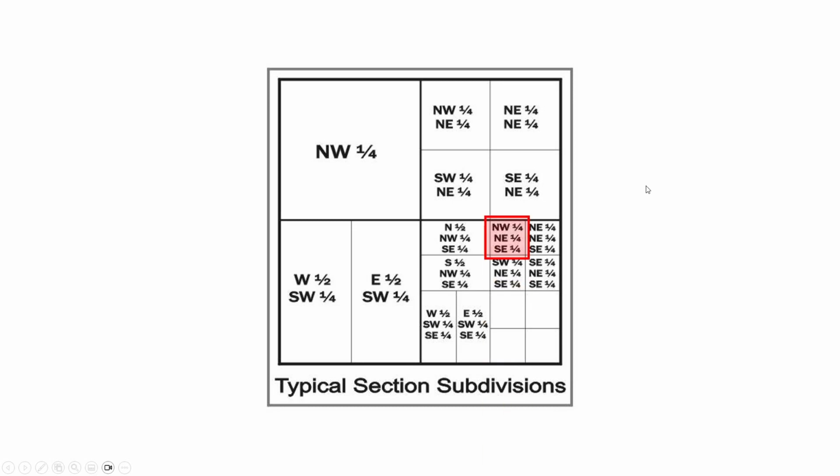But let's add some more to it. So if I go beyond this and I look at this little block here in this section, you're going to see it says northwest quarter. Okay, so let's look at that. How is it northwest quarter? Well, it's northwest quarter of the northeast quarter, which is this block here. This is, and I'll click one more time, that's the northeast quarter. So northwest is that quartered from the northeast quarter. And where's that come from? The southeast quarter. So if I click one more time, you'll see this is the southeast quarter. Okay, so we take that southeast quarter, we quarter it down, and you quarter it again, and that's how you get northwest quarter of the northeast quarter of the southeast quarter.